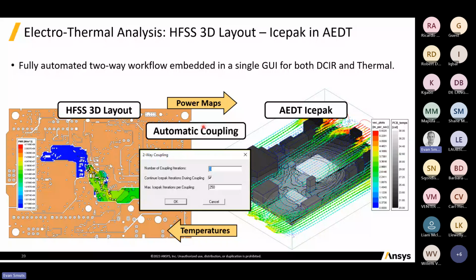Here on this slide, we're just highlighting how, within the electronics environment, we can do a DC power drop analysis. So we can actually look at the power drop in a specific trace, and see where all the hot spots are, where that power is going to be generated more intensely. And then we can take that into IcePack and get a very unique temperature distribution for that specific PCB. And then we can see if we can get sufficient cooling from that, where we position the fans and the casing and other vents and things like that.